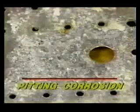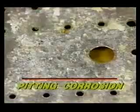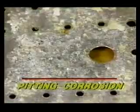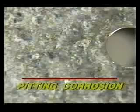Pitting corrosion is the most common form of corrosion found on aluminum and magnesium alloys, but can also occur in other alloys. Pitting corrosion generally appears first as small white or gray dots, and in its more advanced stages, a white or gray powdery substance, similar to baby powder.